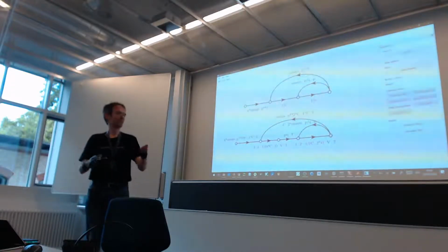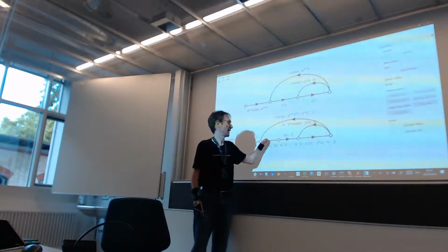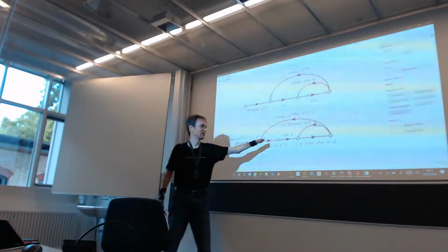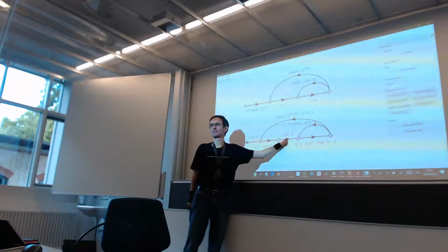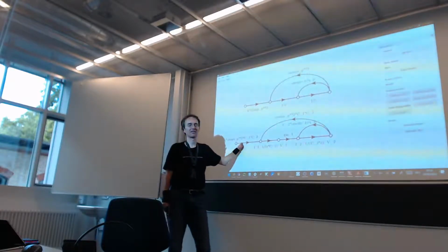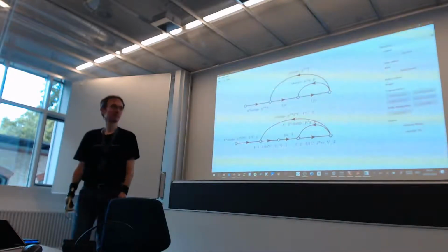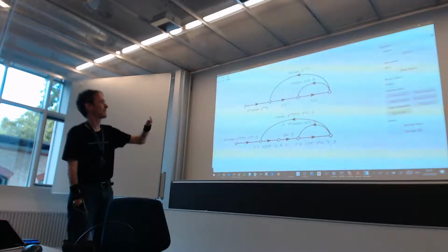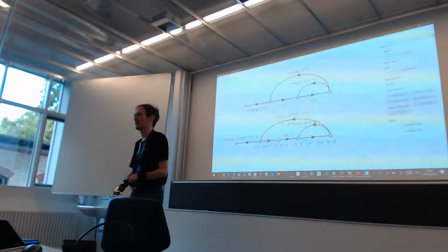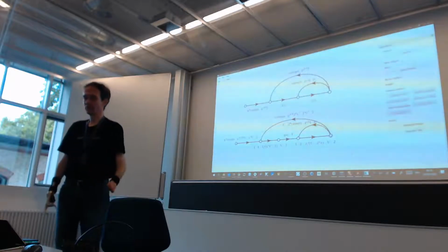So then you can now trade off between the 2 values here and this value here at the input also. So for example, if this should not be 1 Siemens but 1 millisiemens, then nothing bad happens if you make this 1,000 times as large and this also 1,000 times as large, which may anyway be a very good idea, because what you have here right now is very low numbers. So if these are picofarad, these are very small numbers, maybe too small. So suddenly you have a higher degree of freedom.